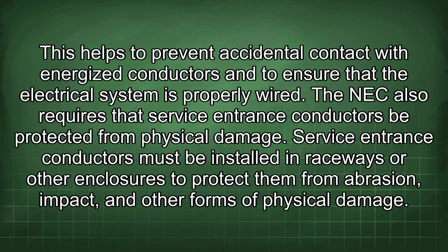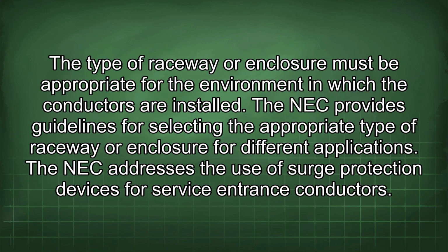The NEC also requires that service entrance conductors be protected from physical damage. Service entrance conductors must be installed in raceways or other enclosures to protect them from abrasion, impact, and other forms of physical damage. The type of raceway or enclosure must be appropriate for the environment in which the conductors are installed. The NEC provides guidelines for selecting the appropriate type of raceway or enclosure for different applications.